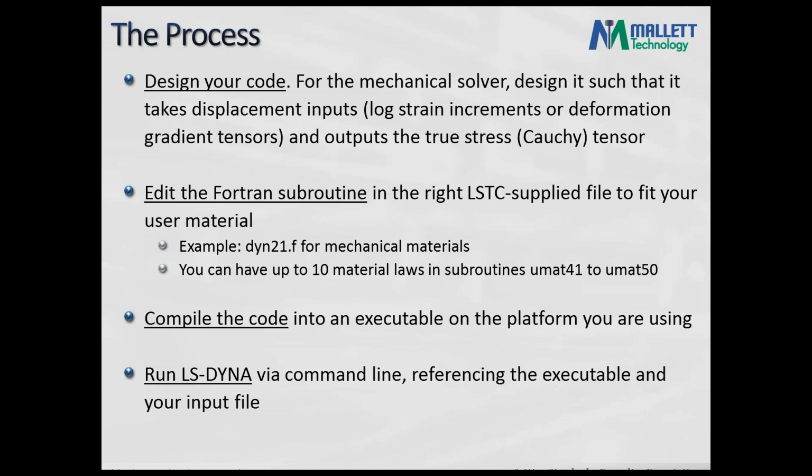And lastly, you need to run LS-Dyna. Although ANSYS has a built-in way to run LS-Dyna, since you're compiling a custom material, you'll need to use the command line to run that custom executable. ANSYS doesn't know how to find it without you helping it out.